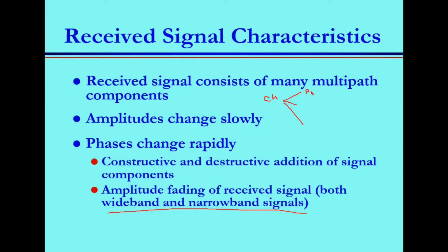Multipath by itself is many types. It can cause three things: delay spread, Doppler, and fading. Now, for each one you need to know when this happens. What are the requirements or the features of the system that can produce such a phenomenon?